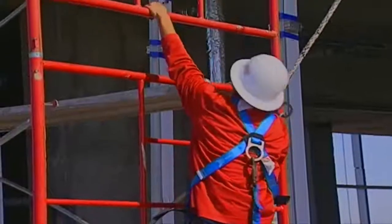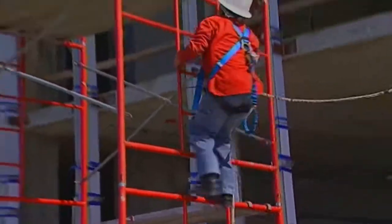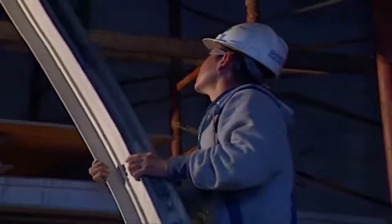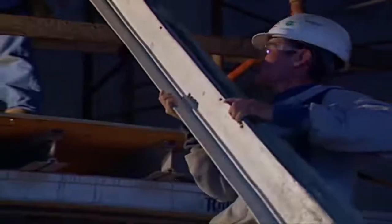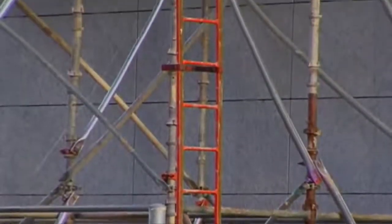The chances of experiencing a fall are greatest when climbing onto or off the scaffold. Safe access must be provided. Workers that erect and dismantle scaffolds are at an even greater risk because the scaffold is not complete and secure when they are performing their work. There are many different forms of access that can be utilized.